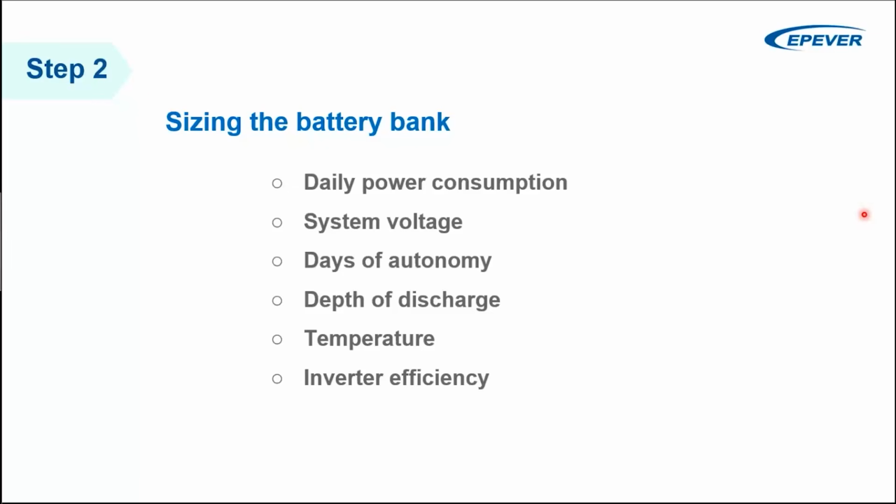The type of batteries used in solar PV systems are deep cycle or solar batteries, which are capable of producing consistent power while being discharged to a greater extent than a typical battery. For example, a car battery is capable of giving you a large amount of current, but for a very short time, and the life cycle is much shorter. The solar battery is much better in regard to the capability of providing continuous power and the life cycles.